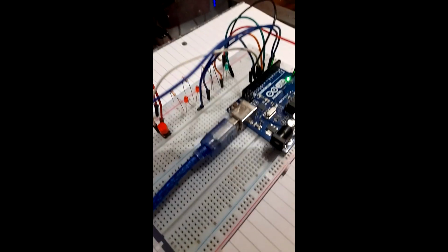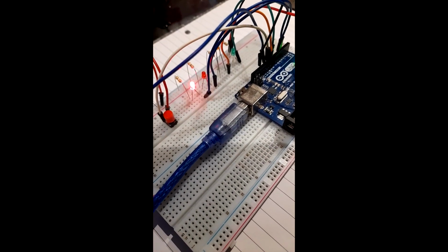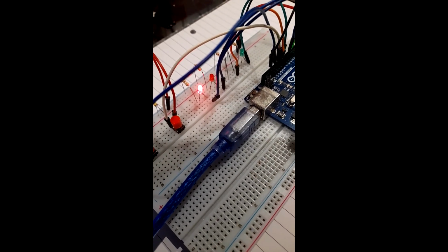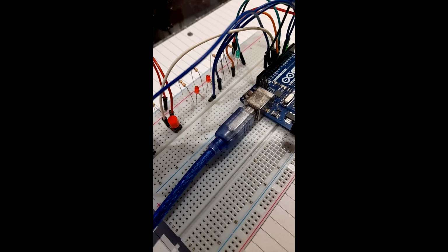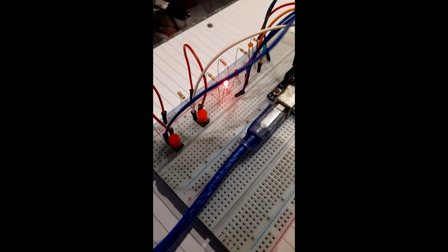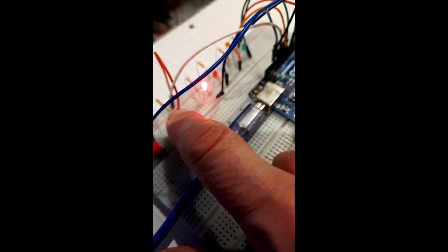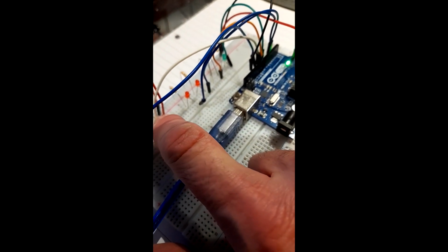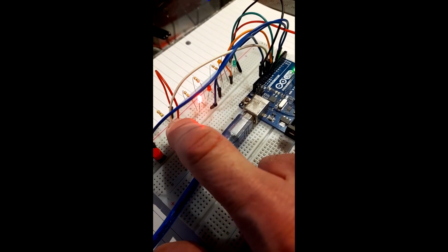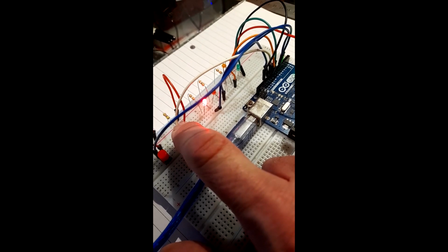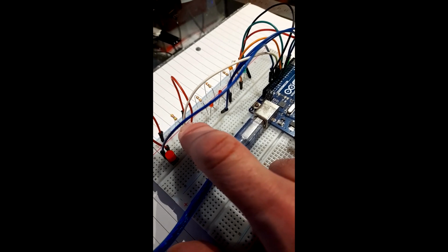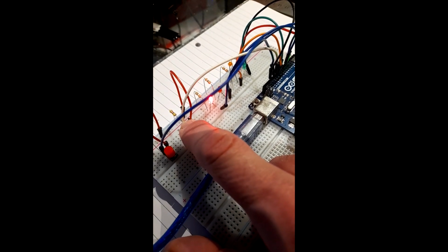Now, in our blocking code example that this Uno is running at the moment, I've got an LED that is coming on for, I think it's 5 seconds, going off for 5 seconds. If I want to control it, which is with this button here, I've got to press it at just the right time to stop the cycle. No, can't do it. I'll be honest, in practice I spent ages doing this. You've basically got to hold the button down and hope you get it. No, still haven't got it.